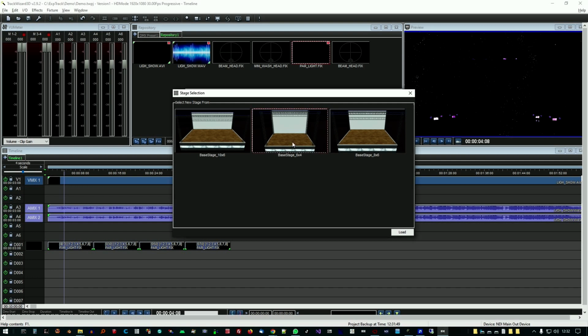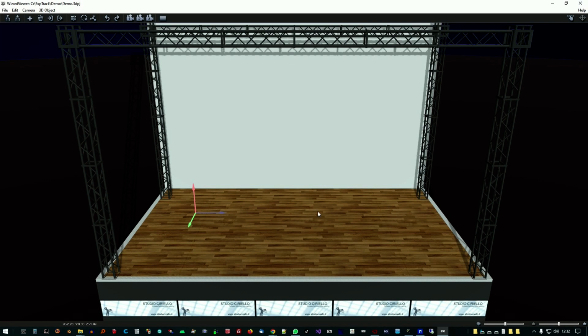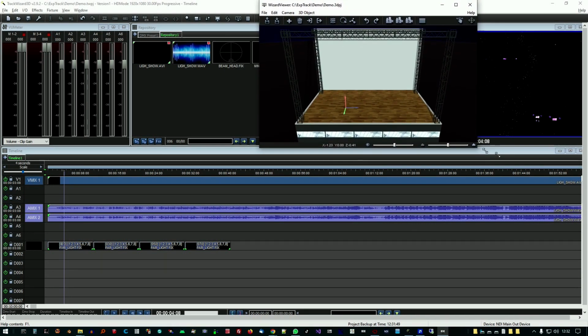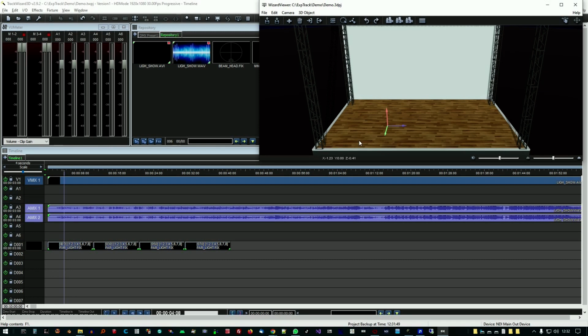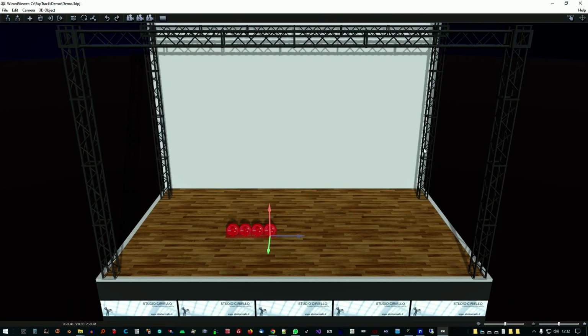Positioning of objects on the stage is done using the current position of the 3D cursor. For example, click on a point on the stage using the middle mouse button. The 3D cursor is positioned in the selected point, indicating the insertion position of the subsequent objects that we are going to add. On the timeline, we select the 4 lighthouses we just added. With the right mouse button, we open the contextual menu and add the lights to the 3D. The objects selected and not present in the 3D scene will be added in the chosen position.